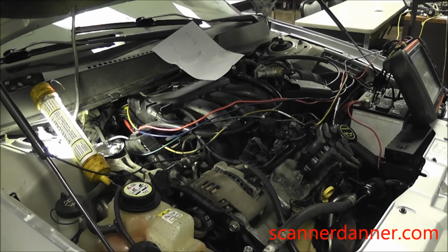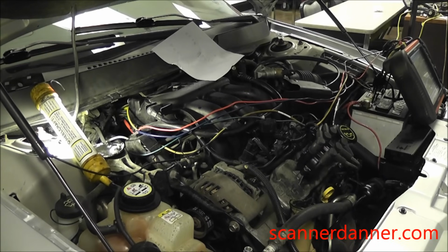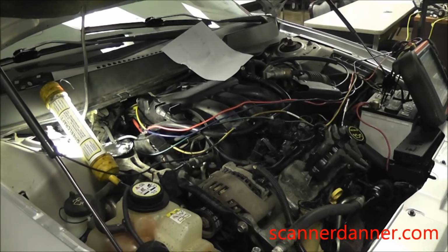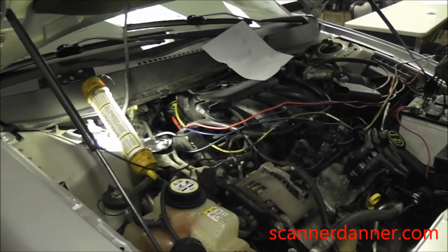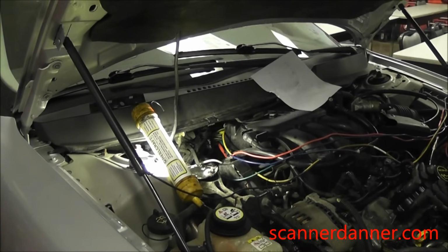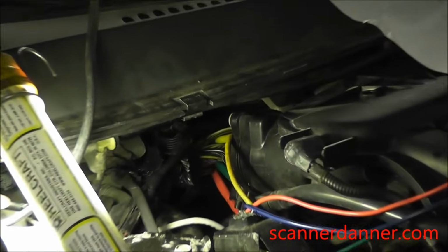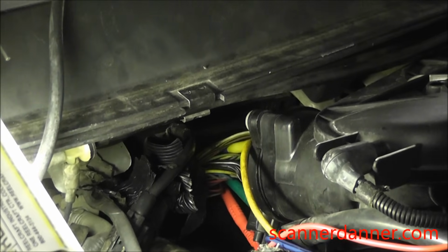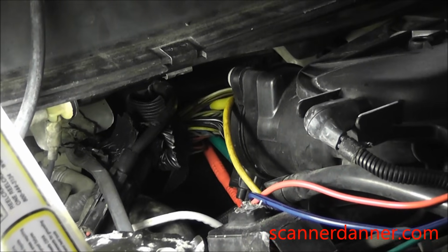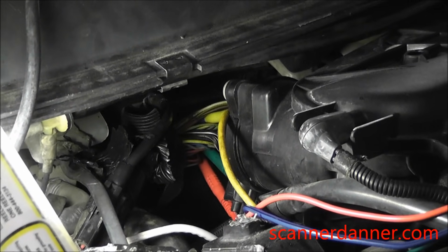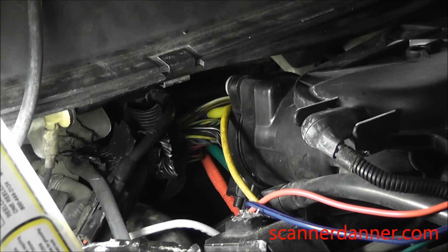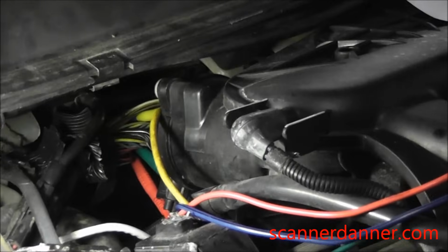For this next segment, what I want to show you guys is the scope tests of this oxygen storage on these cats. And what we've done to connect to all 4 oxygen sensors, we've connected to the engine computer instead of crawling underneath the car and locating the downstream O2 sensor connectors and the upstream connectors too. We went to the engine computer, and this was by no means easy to do. We actually had to unbolt the computer connector and pull it out, find the pin numbers and wire colors, and it was not fun, but we got all 4 O2s connected now.